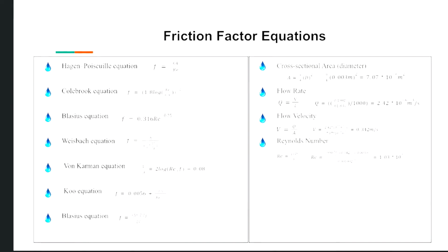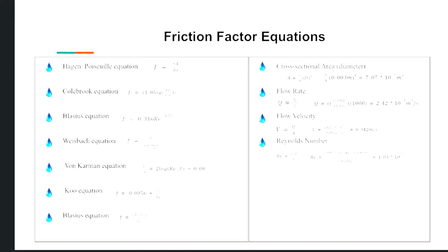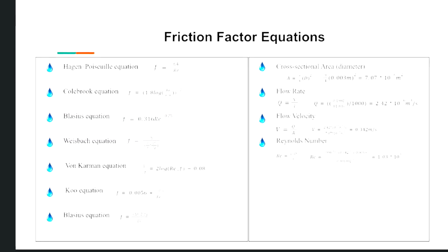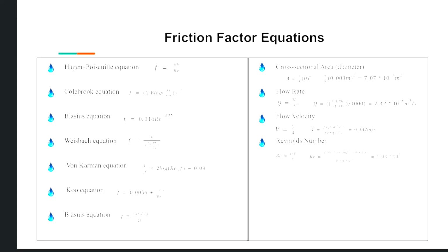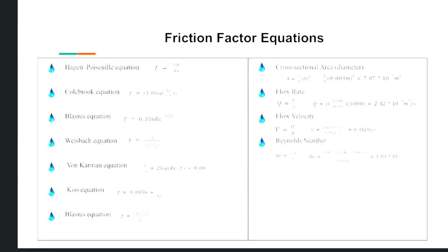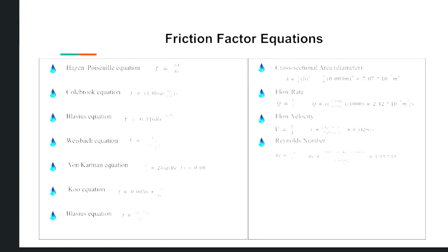There are several accepted theoretical equations used to calculate the friction factor, including the Colebrook equation and the Blasius equation. For laminar flow, the experimental friction factor is determined using the Weisbach's equation, derived from the correlation between head loss and pipe dimensions. The von Karman equation assumes that the pipe is absolutely smooth. The Nikuradse equation is proposed from his experimental data of turbulent flow in a smooth pipe, largely derived from the Blasius equation. To determine the experimental value of the friction factor, Weisbach's equation will be utilized.